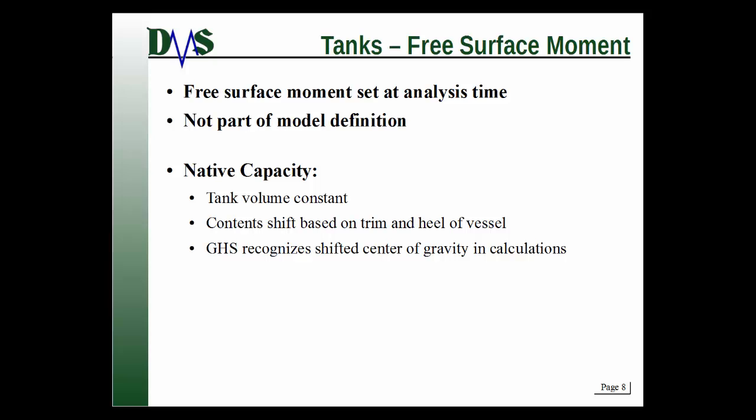Okay, and again, saving the best for last: tank free surface moment. Free surface moment is quite important, and GHS gives you several options for how to calculate it. This is something that you set at analysis time. So when you're building your model in GHS and thinking, okay, how do I set the free surface moment for my tank? Don't worry about that. You don't set the free surface moment when you're building the model. You do it when you're actually using the model in analysis. So we'll come back to that in later lessons.